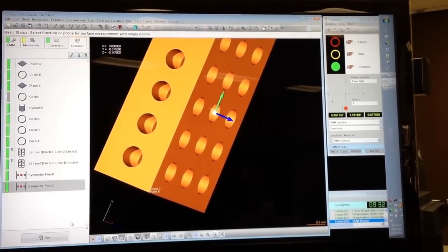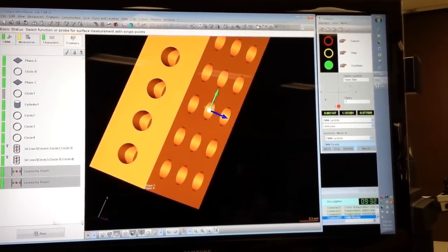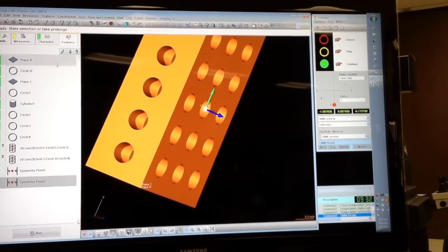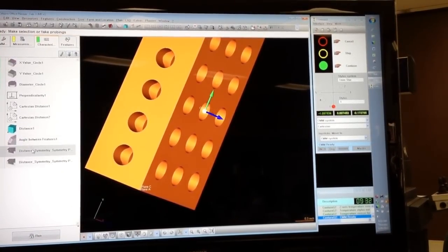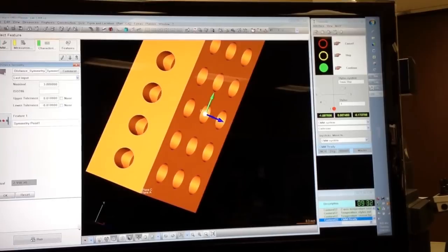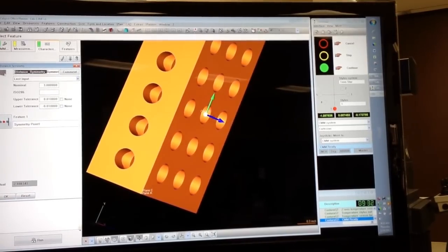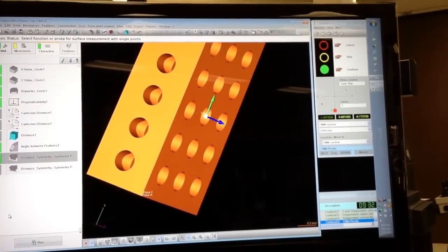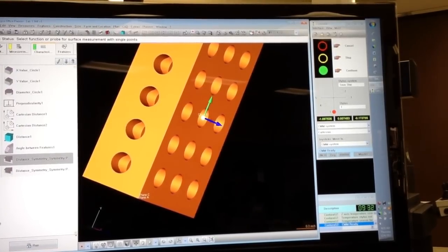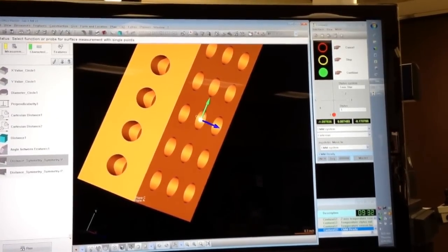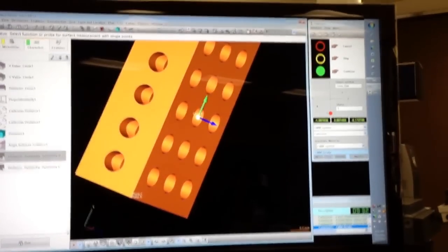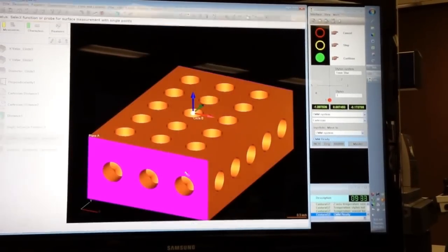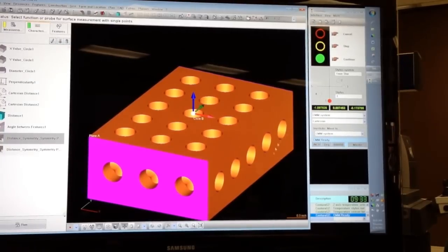And by the way, we will now test run both of those. F9, and looks good. And yes, those did generate these specific characteristics with these very long names on them. Those are names that are worthy of shortening a little bit. Next, we have the true position with MMC of the 5 holes on the right side of the block. That's these 5 holes over here.